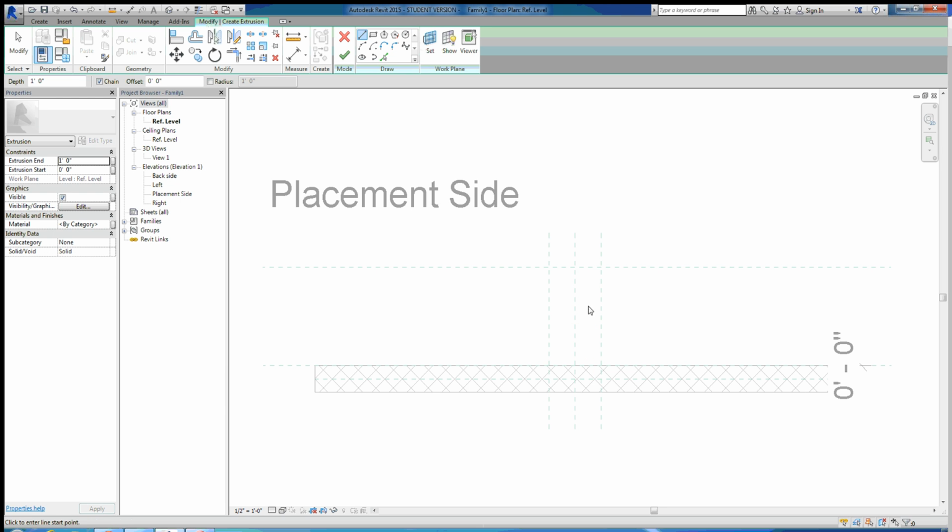That means when we're creating something in 2 dimensions, we have to always keep in mind what's happening in the 3rd dimension, in that Z direction that's going into and out of the screen. If you look over here, that's where this comes into play, this extrusion start and the extrusion end. For our water fountain, we start 27 inches up, and then we know that the thickness of our water fountain is 6.5 inches. So we want to end at 2 foot 9.5 inches there.